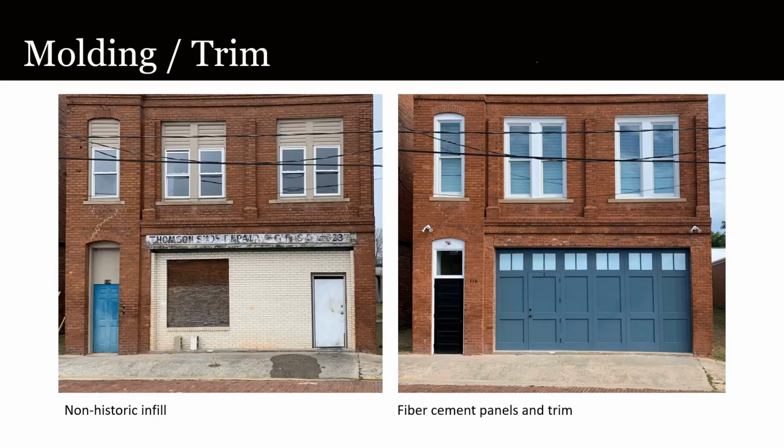Simple flat boards over panels were all that were needed to execute the design. Without the moisture-driven movement of wood or cellulose composites, or the temperature-driven movement of cellular PVC, it should provide a relatively stable assembly that will not be prone to paint failures. The material is not recommended for ground contact, so one might hope that the small concrete curb on which it sits is minimally adequate to prevent any moisture absorption at the bottom of the assembly.